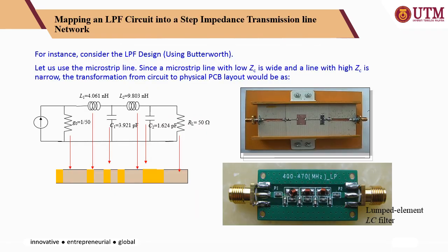Okay, next, another practical implementation of the filter design. Again, another low pass filter, for Butterworth. The first step is to get the circuit realization from calculation. Then you get the filter order number. Then you determine the normalized elements or the components in your filter circuit, and then put the design into your simulator.